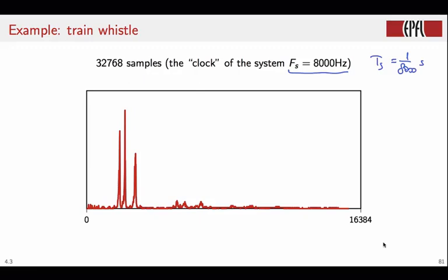Now, in order to label the axis, remember what we said. The highest frequency for a digital system corresponds to half the inherent sampling rate. And on the DFT vector, this point will correspond to the midpoint in the vector, namely the point for k is equal to N over 2. So here indeed we have the midpoint of the DFT vector, and therefore this will correspond to a frequency of 4 kHz. We also have 3 peaks that take place for different values of k.